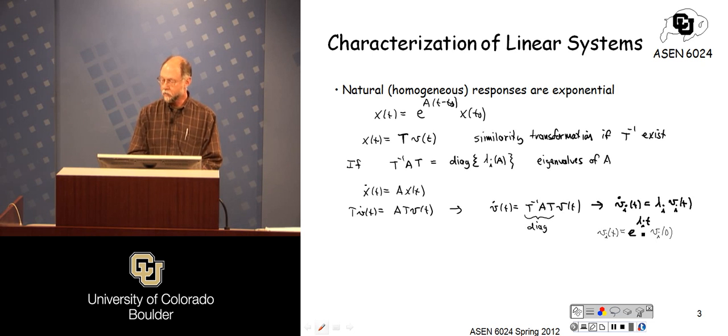Well, then I get complex vectors here, complex coordinates here in the state space. So you can do that. You can decouple this as long as this thing diagonalizes. Those diagonal elements, some of them might be complex, if the eigenvalues of the A matrix happen to be complex. So you can still do that, but then you get complex signals here, which is kind of disconcerting, except that those eigenvalues always come in conjugate pairs.